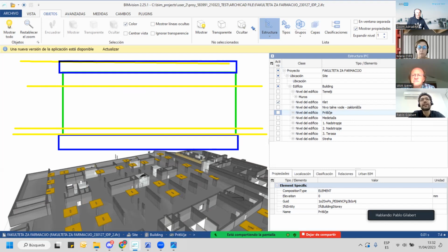We can have a lot of different levels, but you know, there is an option in ArchiCAD and Revit where we should mark, okay, this level defines a floor. This level also defines a floor, but this one doesn't. In this case, they included this level as a floor, and it's not right, but it's not a huge problem for us either.